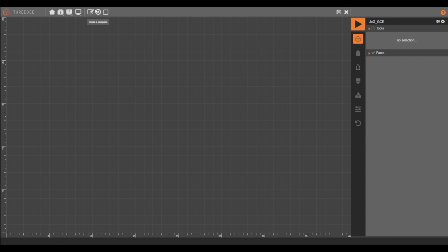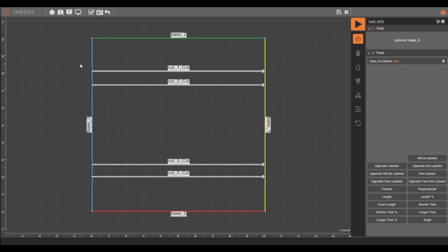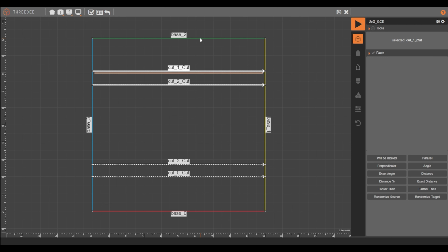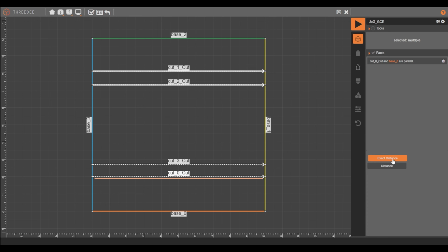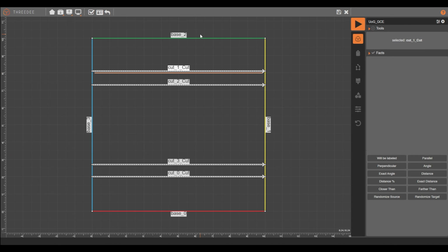We will then create a select node, selecting the labels that we just applied in our base, sides and center. Combining cut and select nodes will allow us to form the basis of the structure and also allow for precise alterations later on. From the sides, we will create another cut node with 4 cuts that will be parallel to